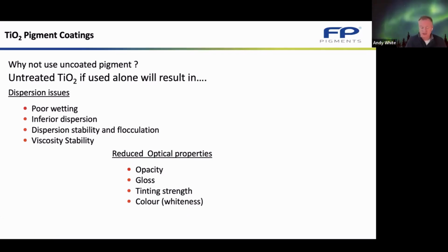So essentially, the surface treatment of the TiO2 is vital in delivering, first of all, dispersion stability, so that you can actually put the TiO2 into whatever media it needs to go in, because there are different surface treatments for different applications, and then achieving that spacing of the TiO2, that good stable dispersion that, when the coating dries, is going to give the light scatter that you require.